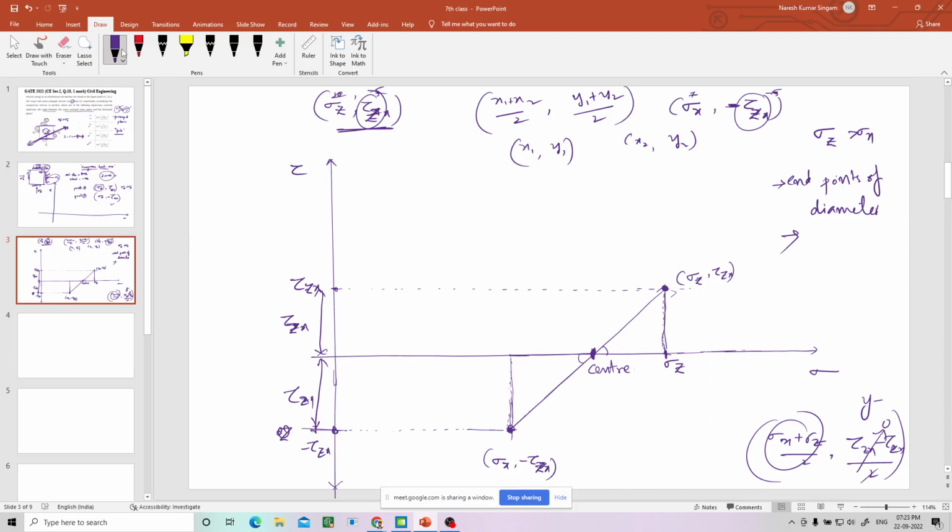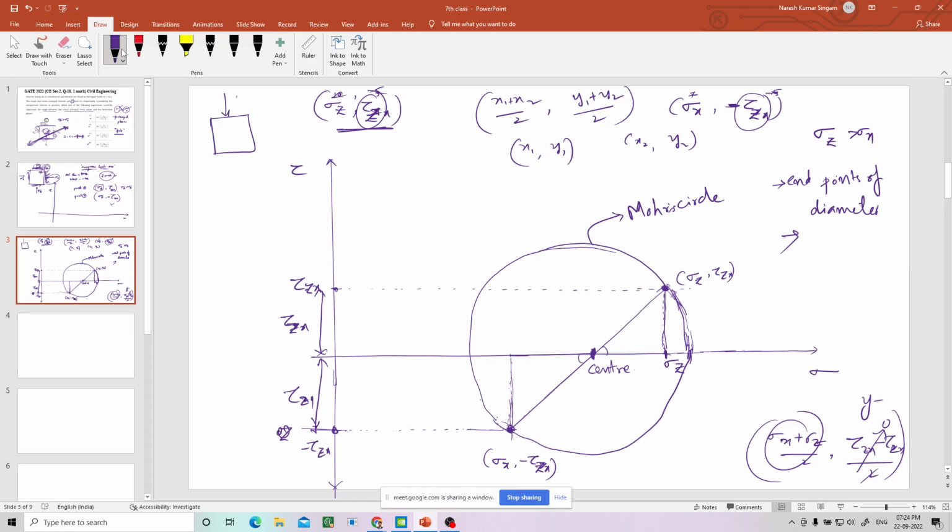How can we do that? Just take a compass and you can finish it off. For the time being, let me draw. It may be a bad circle. Now this is the circle, the Mohr circle. I have drawn the Mohr circle with the 2 points. The given data is over now. You have drawn it by taking the given element. The element was given with sigma z and sigma x, and then there is some shear stress here, tau zx and tau zx.